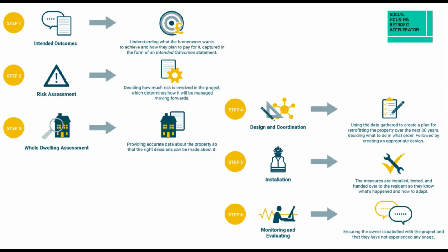That then goes through a risk assessment process, and basically what the risk assessment process is there to do is identify the fundamental conflicts between different measures. So where there are potential issues with regard to thermal bridges, with regard to needing coordinating specifications, needing coordinating details. And that's to make sure that we understand the level of risk of the project, we understand where key details and specifications need to be produced, and then the PAS defines what qualifications of retrofit designer needs to then produce those details and those specifications.